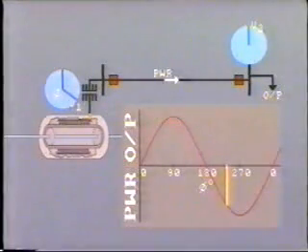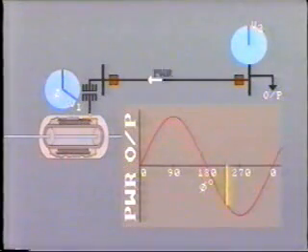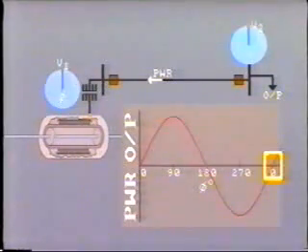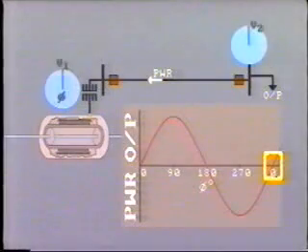As the advance continues, power begins to flow in the other direction, that is, into the generator from the system. The generator rotor has advanced so far that it's now coming around again and is beginning to catch up with the system. It then reduces to zero as the angles coincide. At this instant, the voltages at each end of the line are in phase, and load transfer is zero. All this has happened in about half a second. The turbine governor has hardly had time to act yet, so the generator rotor continues to accelerate.